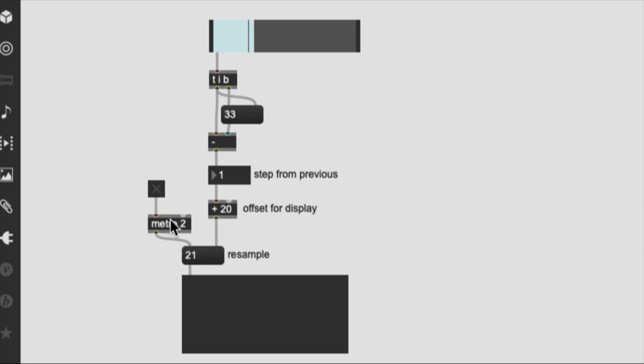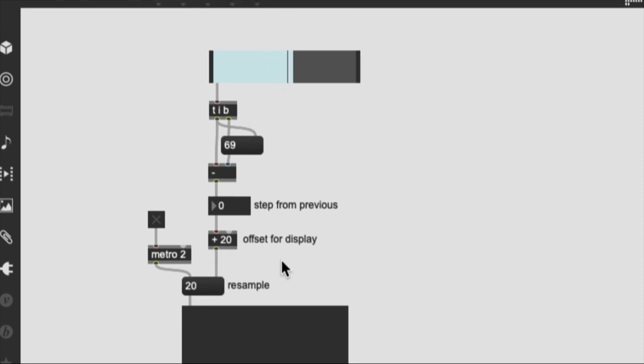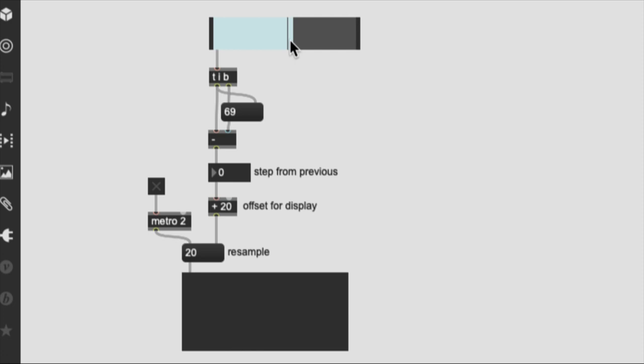And this is really crucial, because you see the numbers come out of the slider only when something happens. But in order for me to get a velocity estimation, I would have to estimate that it's not moving now. I would have to get a zero velocity. But without any values coming from it, I could never do that, right? So therefore, I'm resampling it. I'm making sure that I get values all the time. So this is my actual zero. I've done an offset here. It's not an absolute measurement. And here goes my estimation.